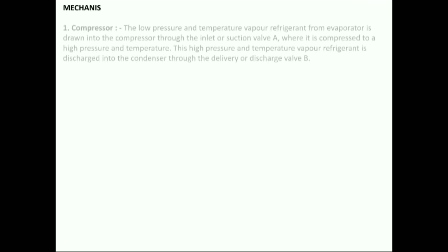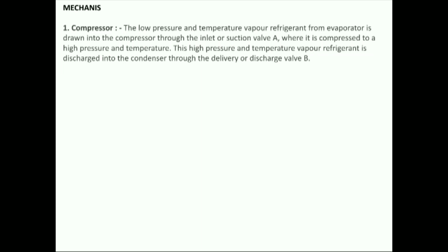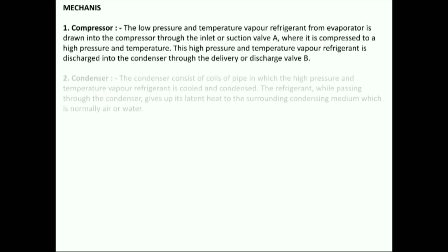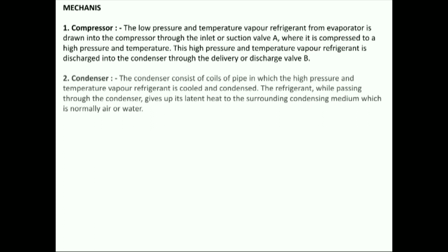Mechanics. 1. Compressor. The low pressure and temperature vapor refrigerant from evaporator is drawn into the compressor through the inlet or suction valve, where it is compressed to a high pressure and temperature. This high pressure and temperature vapor refrigerant is discharged into the condenser through the delivery or discharge valve.